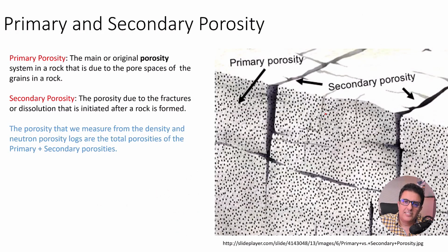You may have noticed that estimation of the porosity from sonic data is not that straightforward. It's very challenging, so we have to consider so many factors. We have to have some idea about lithology, the fluid in the formation, and also the state of consolidation, and whether we have hydrocarbon or not. So it is a lot of challenge.